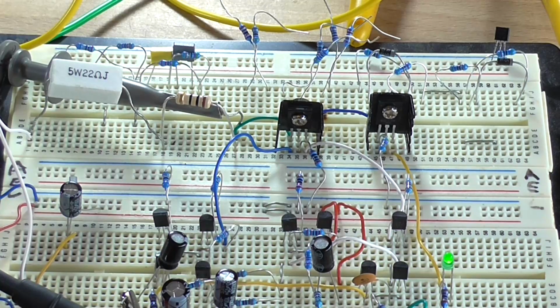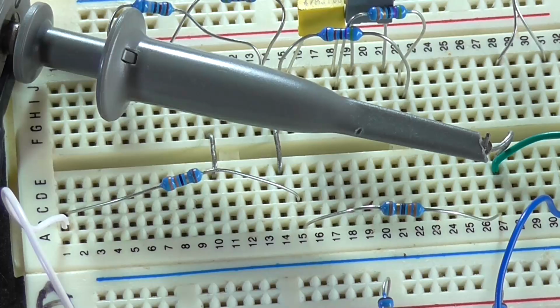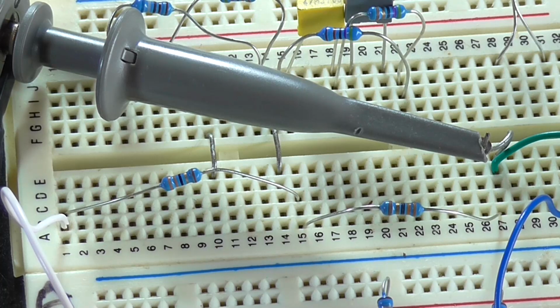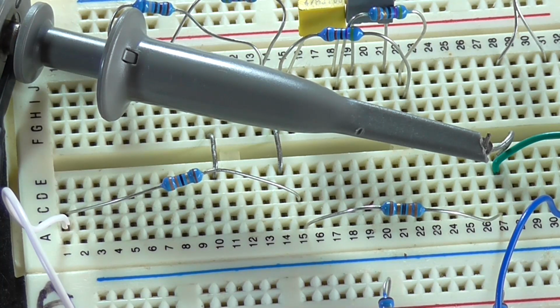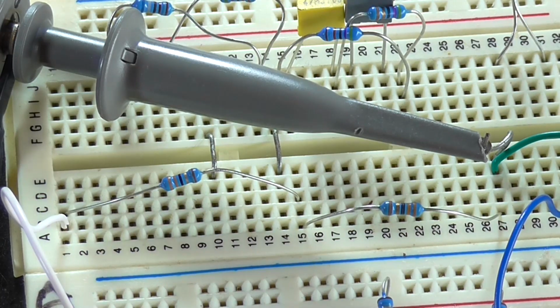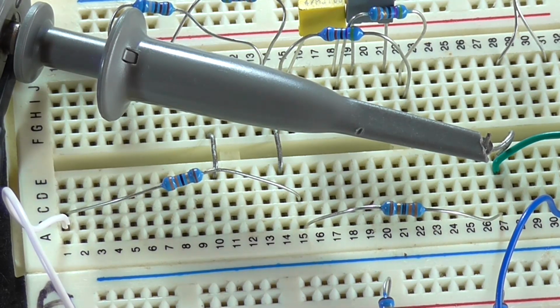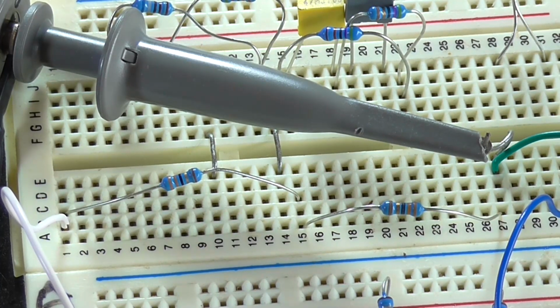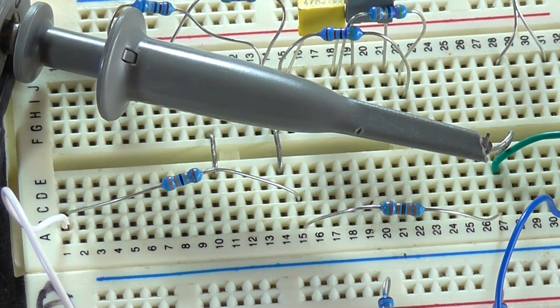Now I've got to make 64 ohms, which is going to be a little bit more of a challenge. I reckon I can come up with something. That's highly inadequate. I've got two half watt 33 ohms in series. And that should give me an equivalent resistance of around 66 ohms, which is about as close as I'm going to get it with my standard values that I've got. It's not ideal, but for this quick test to measure its power output, it will be sufficient enough.